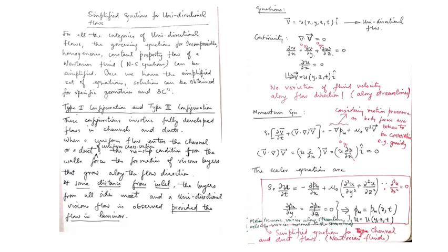any velocity terms, so they just give me very elegant looking expressions for motion pressure. del Pm del y is equal to del Pm del z is equal to 0. So it shows that motion pressure does not vary along y and z directions. Now this is where it is advantageous to work with motion pressure, because if we were to retain the body forces in the original equation, then those body forces, if they have components along y and z directions, they will lead to some variations in pressure.